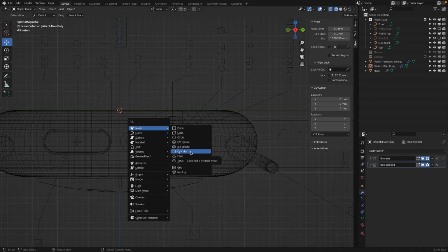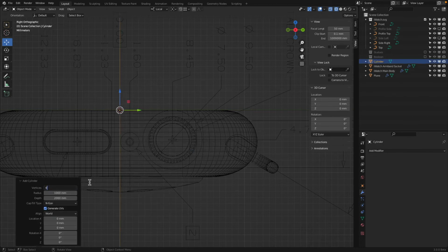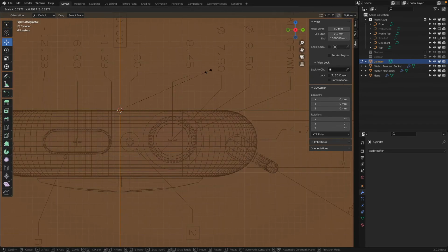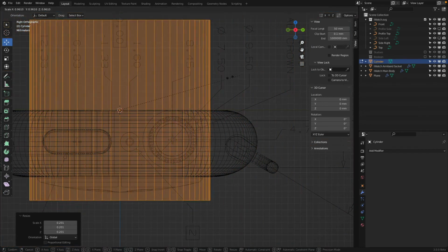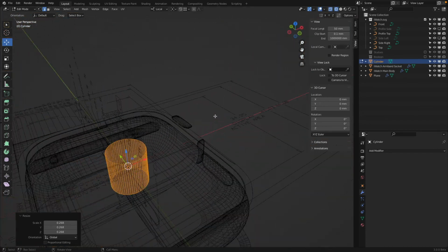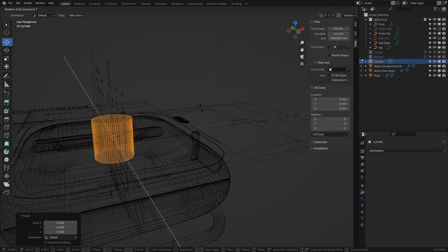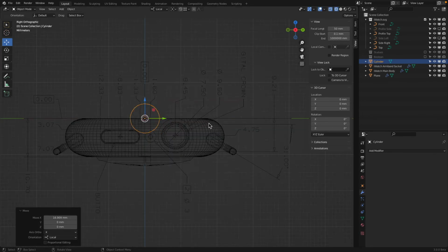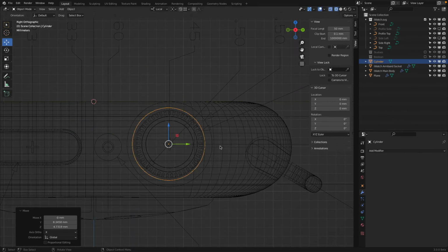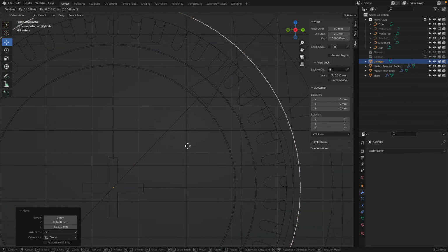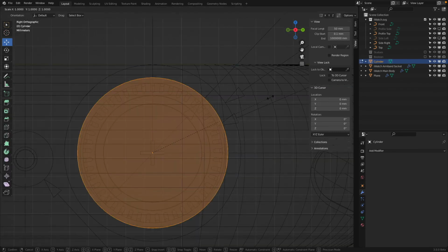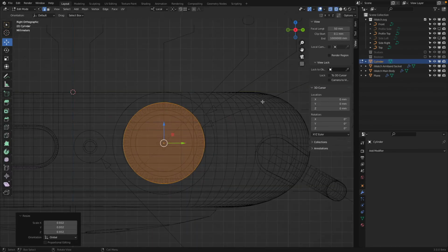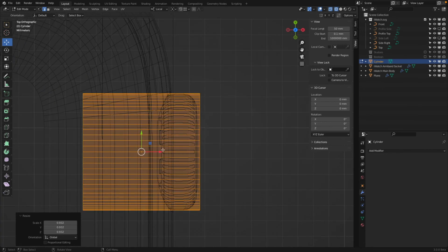We will start with a cylinder. The cylinder we make 64 cuts. Okay, good. And then in edit mode, I simply scale this one down. I'm RY and 90. Very good. In object mode, I move this one then over and position it. Kind of like there. Okay, in edit mode, then again, S scale this down. That seems now to hit the proportion.